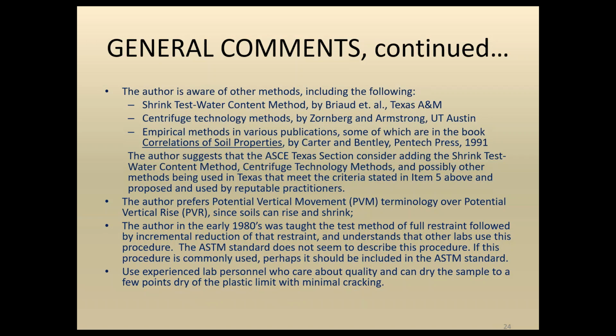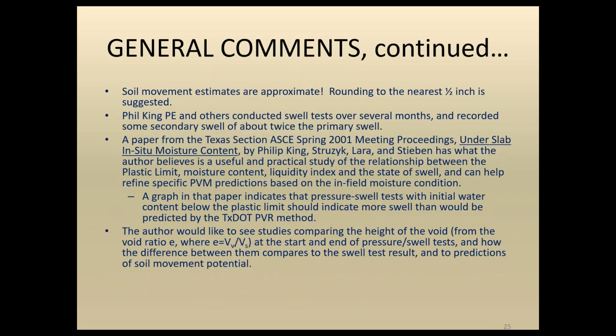A comment on just lab personnel. I'd suggest using the experienced lab personnel who care about quality and can dry the sample to a few points dry of the plastic limit with minimal cracking. It requires some judgment and care for quality on the part of the lab person running the test. Additional comments. As I mentioned earlier, soil movement estimates are approximate, and I'd suggest, in the way our industry reports them for clients anyway, in the world of actual construction, that rounding to the nearest half inch is suggested.